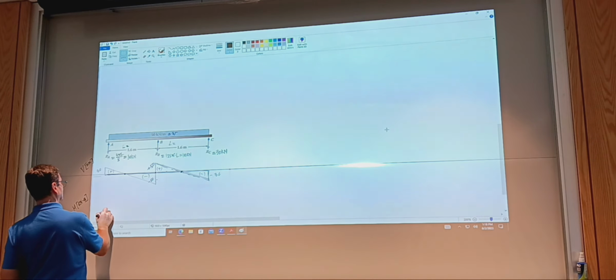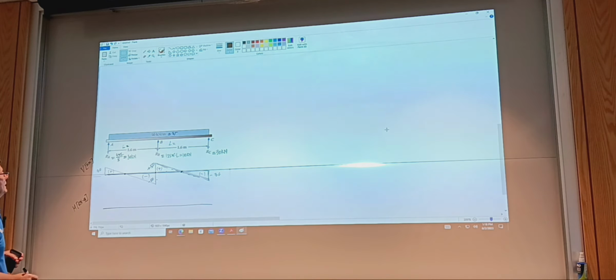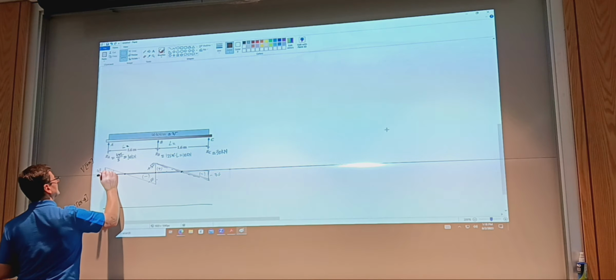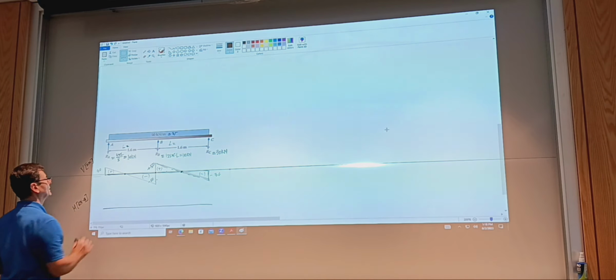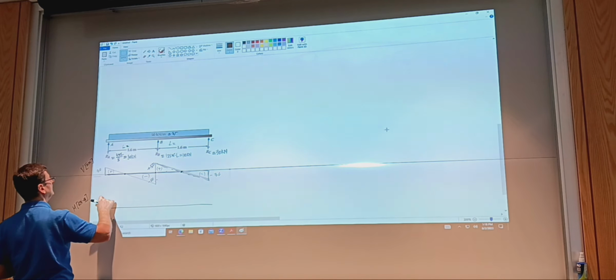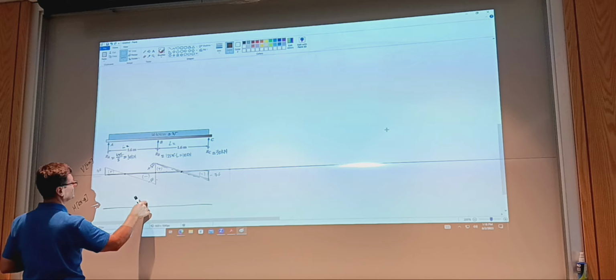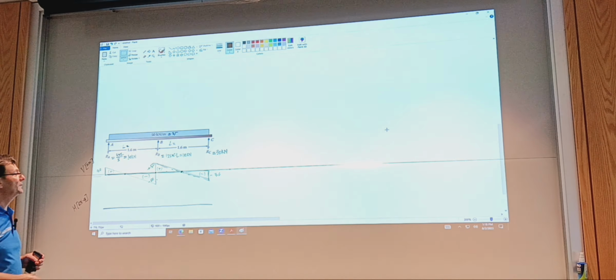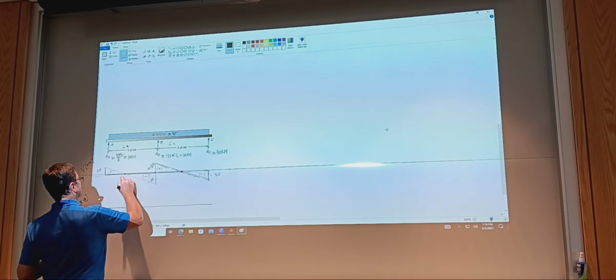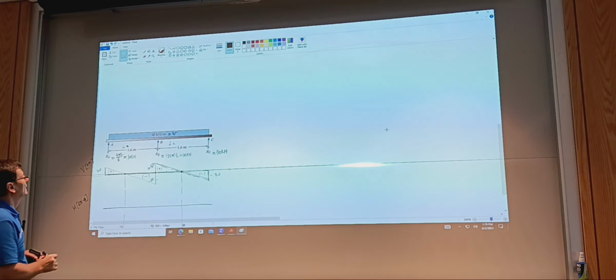So let's see how our values get combined. So the x-axis, and since the load is uniform, the moment diagram is a parabola. I start with a positive 30 kilonewton slope that goes to 0 and then continues and goes to negative 50. So there will be a max where the shear went to 0, yes.